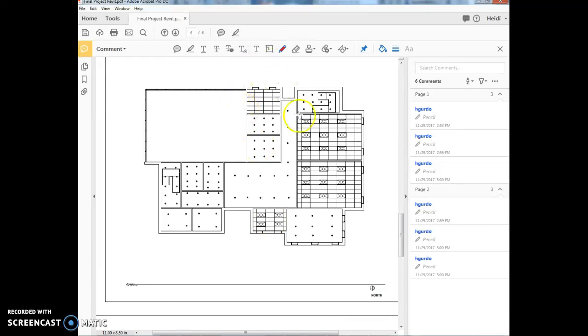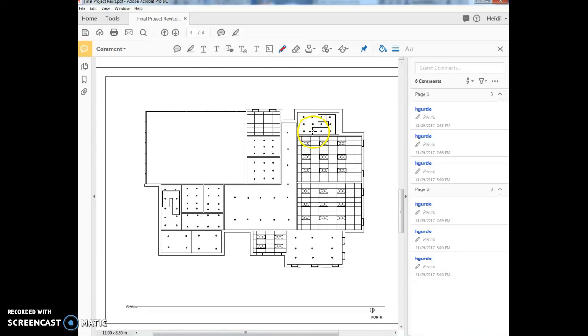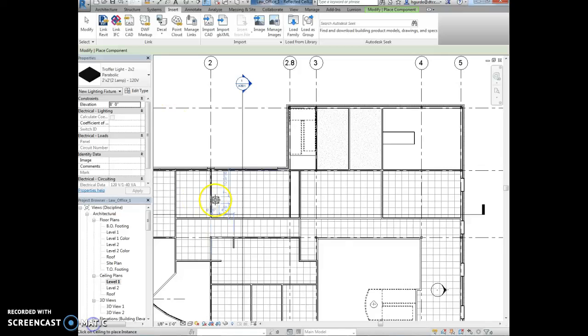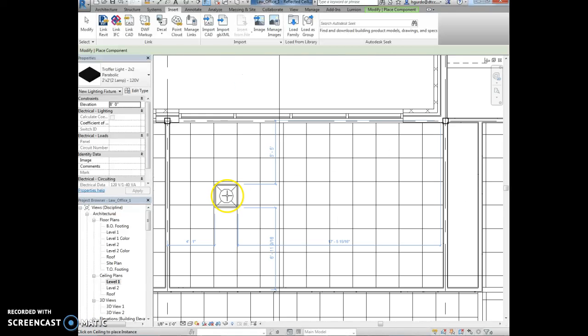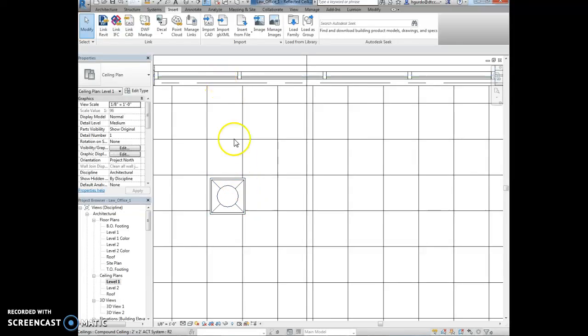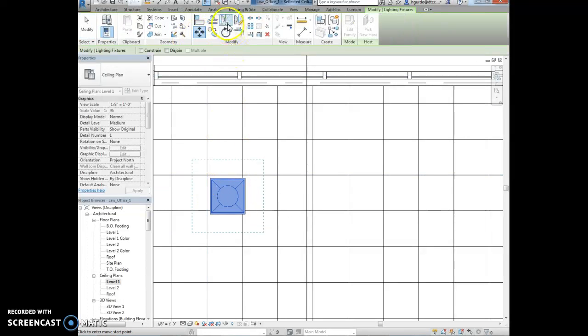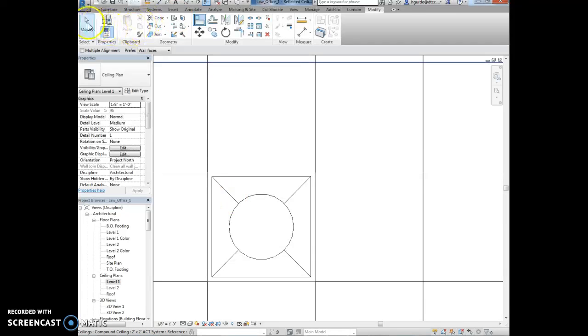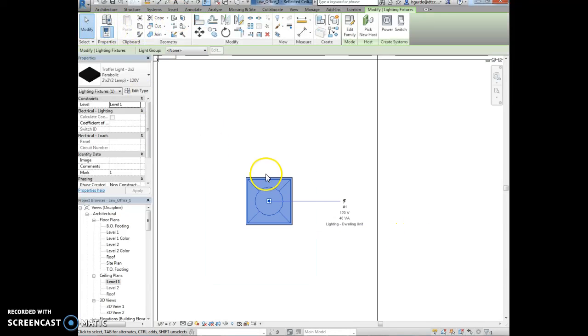To center the lights in the space, one thing I see is it looks like your lights are not snapped to the grid. So let's talk about that first. The trouble with Revit is it really doesn't have a good way to snap them. It just doesn't do it. It's kind of a bad feature. So I usually place them way offside of the grid so that I can then use the move tool, or I can use my align tool and have that object aligned. But make sure that it is right to that grid. And then you can even lock it in place.